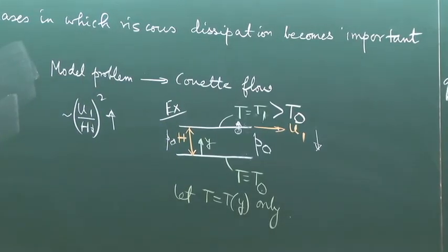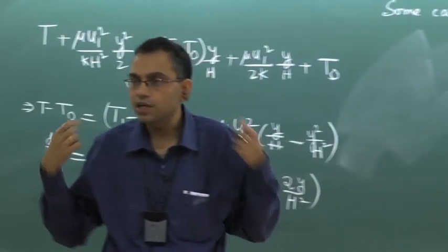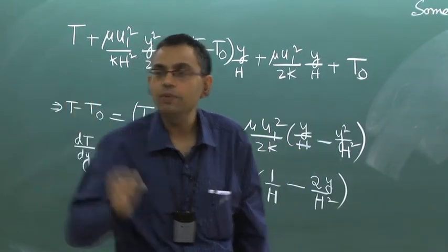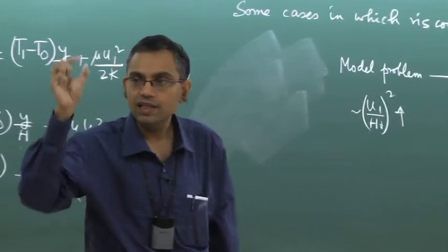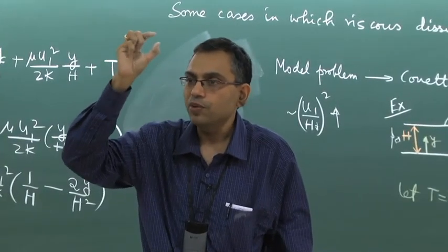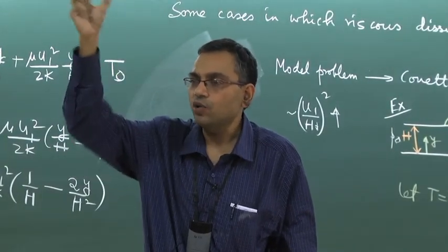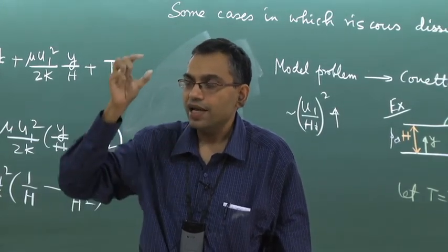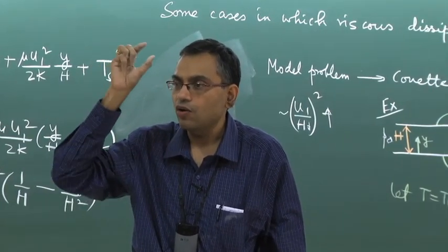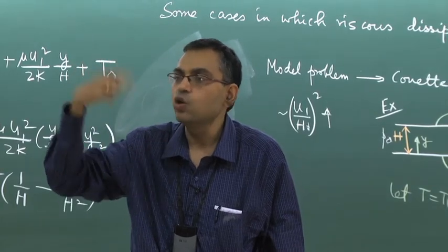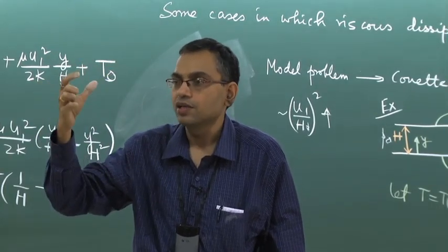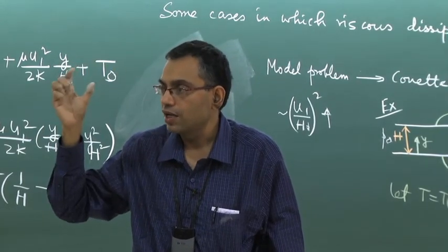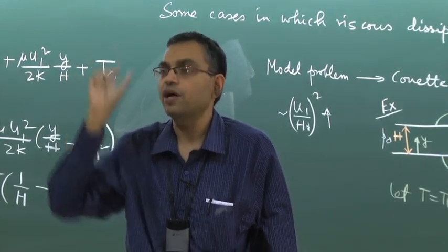So one can understand the temperature distribution, the heat flux, and so on in bearings. And why temperature in the gap between the shaft and the outer casing is important? It is important because the entire functionality of the oil, which is say a lube oil, depends strongly on the viscosity of the oil, and the viscosity of the oil is a strong function of temperature.